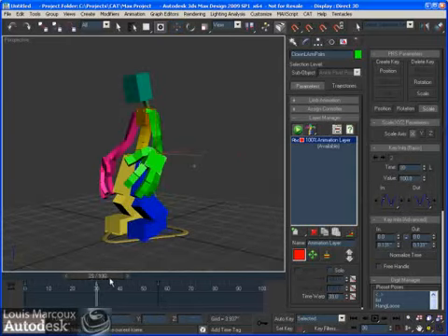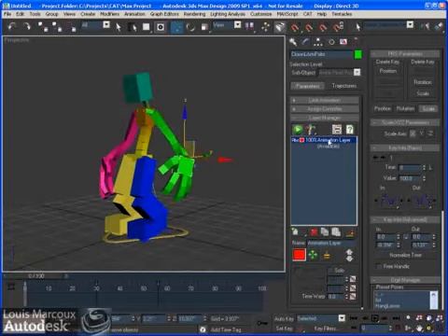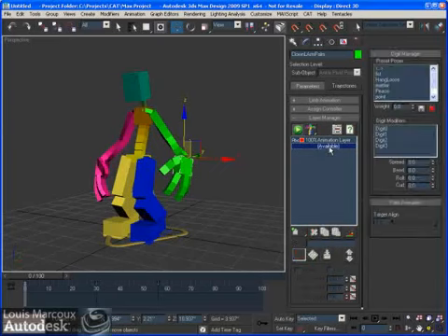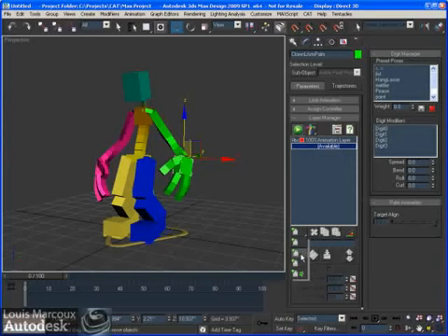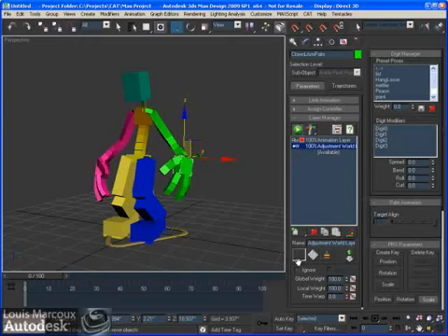So of course I don't want to go and adjust all of the keyframes. I want to adjust the animation layer itself. So I can go into the available slot here, and I can create a local adjustment layer or a world adjustment layer. And basically, most of the time you will want to choose a world adjustment layer. So if you don't understand after this video the difference between local and world, just grab the world one, and it's going to behave like you want it to.